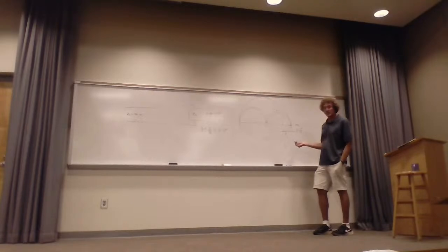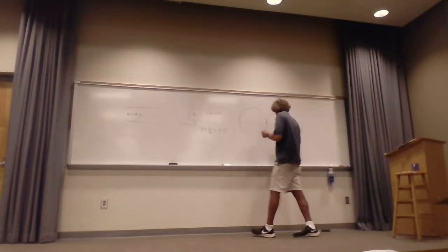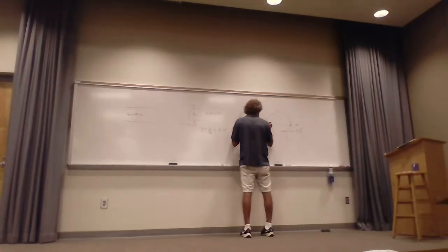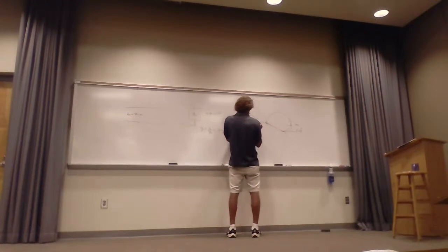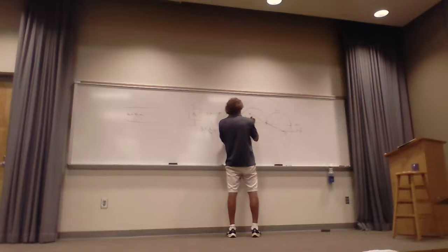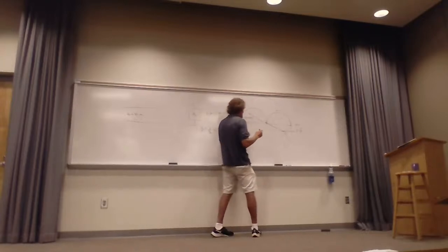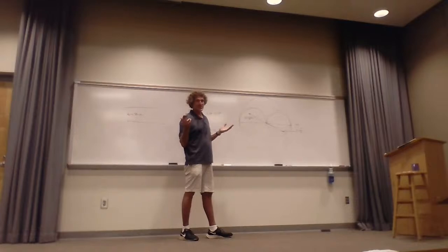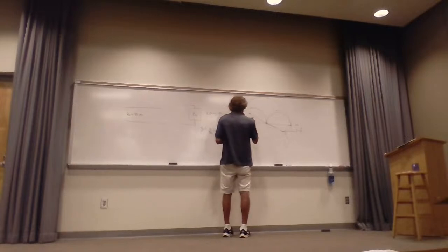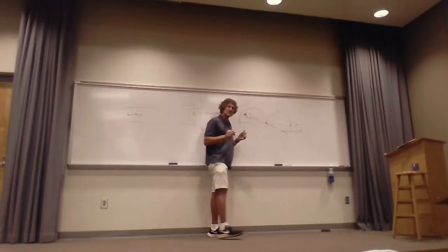Obviously, it's inside the one circle. Nothing I add in series will help me. So I need to go to the admittance domain. I take 1 over that. And I come up here. And this will be 0.1 plus J 0.1. The reason I know is because I look. You can do it if you don't believe me. It's in the book. So that's the first point. Here's my second point, really, 2. And this is YL.